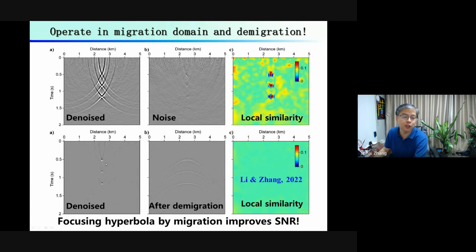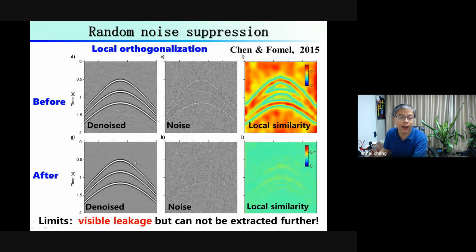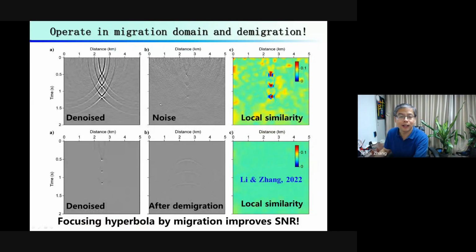So these three points are signal from the reflectors, even though they may be very tiny or very weak. On this trace, the signal to noise ratio is very, very low, and in many other traces, it's the same case. However, after migration, the hyperbola has been concentrated, or focused, to the scattering points. That means the signal in these traces is much larger than before.